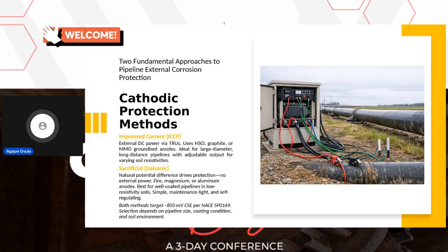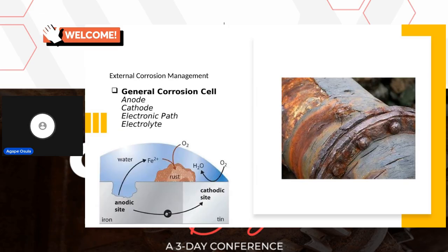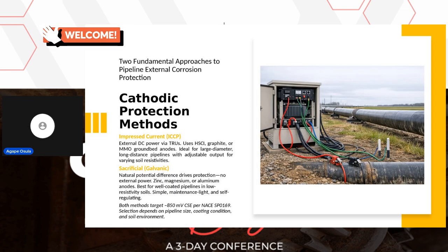All we do for galvanic cells is connect another anode to what we want to protect, and then let the anode corrode. That is the same concept of protection we use for the galvanic or sacrificial system. Of course, the impressed current system is a little bit different. For that, we send in current to charge up the material itself to a region where it cannot corrode.